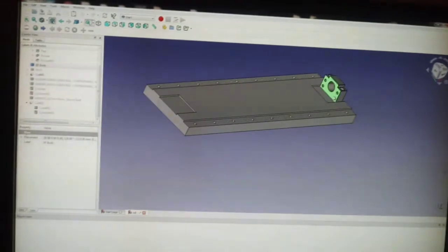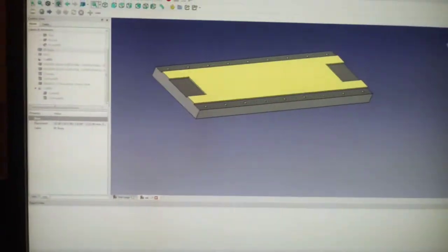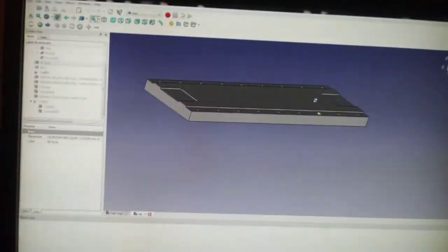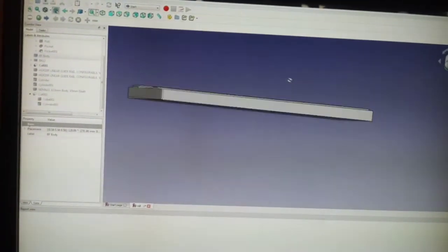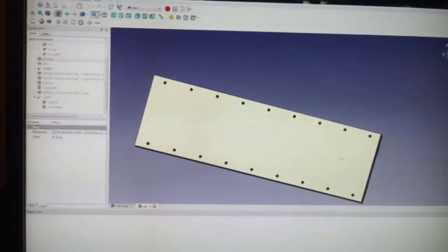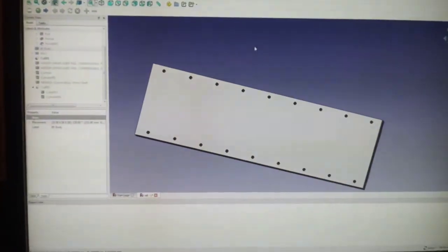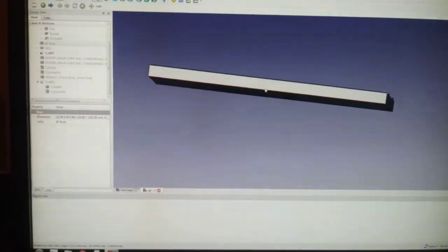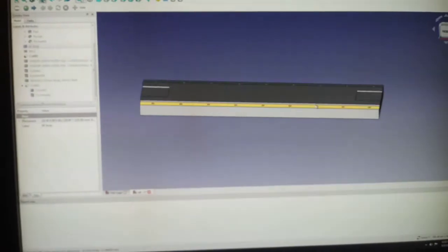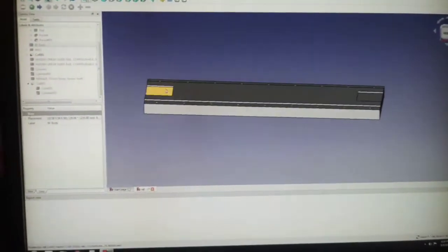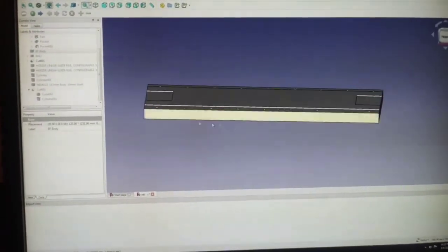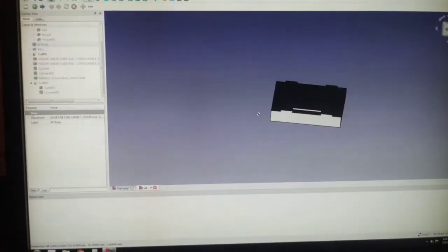Anyway, getting off track here. This is the plate that will be the 1x6 piece of steel. What I'm going to do is this side I'm going to mill flat first. Then I'm going to put this in the mill the other direction, milled side down. I'm going to mill this side flat and then put these channels in accordingly.